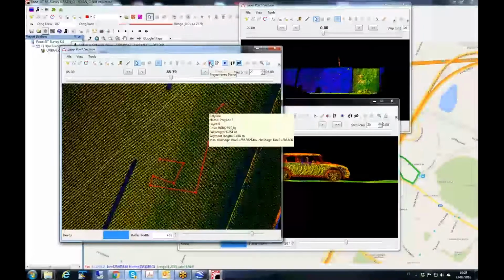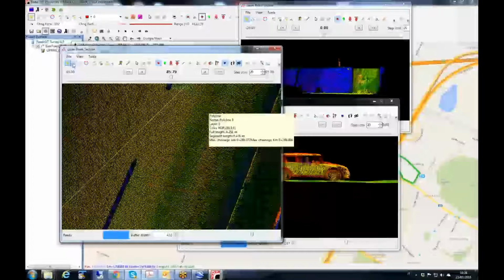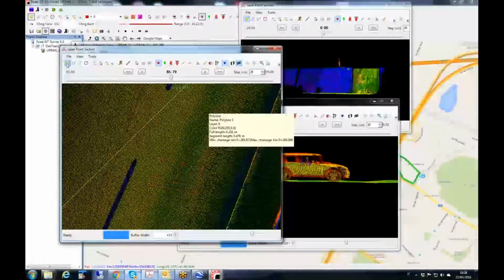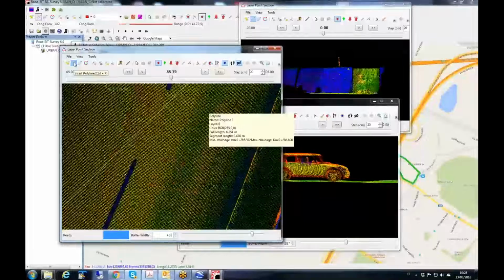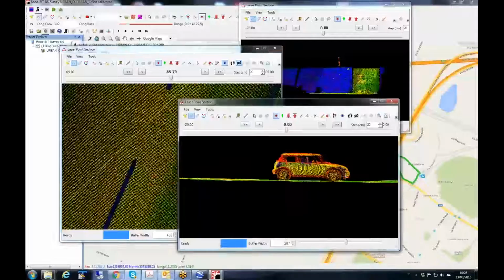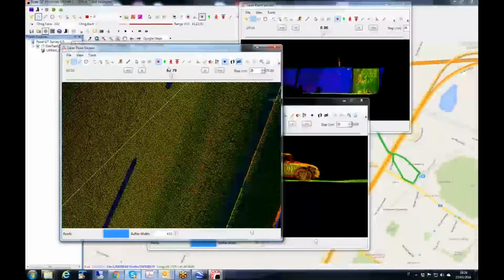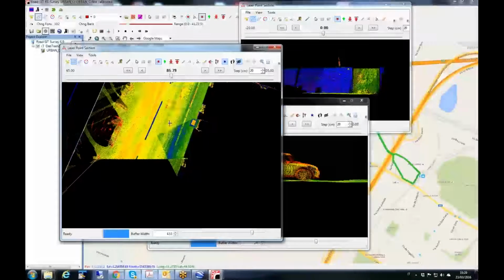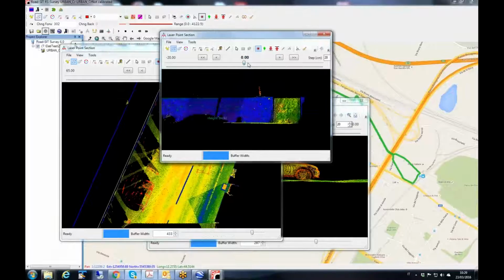In this case, you see that if I move the position of the plane, in this zone the section is moving. And if I want to draw exactly on this white line, I can enable this project onto plane, and when I draw, I'm actually drawing on this line. This is exactly the last line I've drawn, so you can see it exactly on the section position.